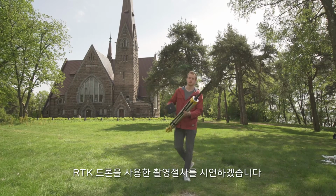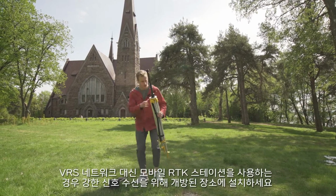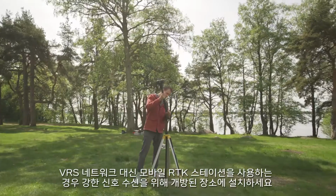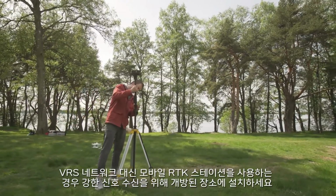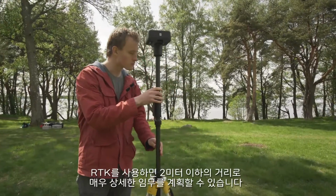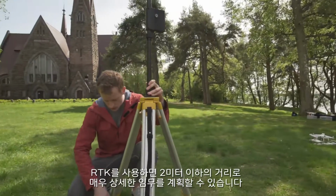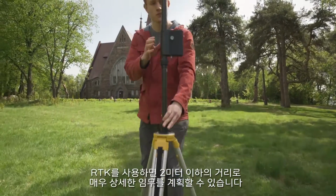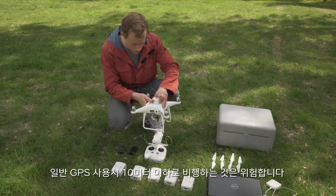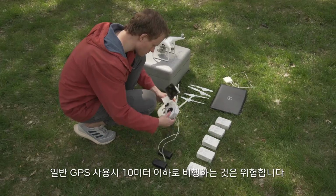We will demonstrate the workflow related to an RTK drone. If you use a mobile RTK station instead of an NTRIP network, mount it in an open area to prevent GPS signal shadowing. RTK allows you to plan highly detailed missions with short capture distances down to 2 meters, while regular GPS navigation makes it dangerous to fly closer than 10 meters to the surface.